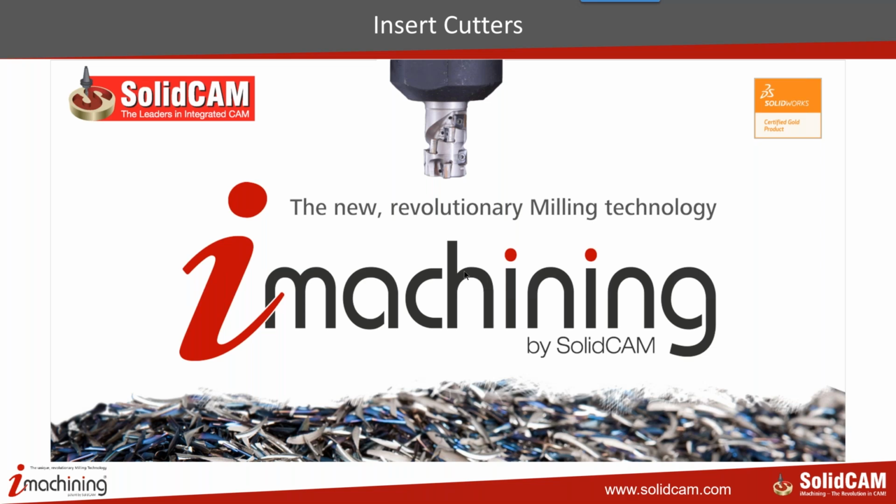However, since the variability of the geometric and mechanical properties of porcupine indexable insert cutters and their inserts is much higher than that of solid carbide end mills, and since metals react differently to being cut by such porcupine cutters compared to being cut by solid end mills, those algorithms had to be modified to take into consideration all those new properties and had to be recalibrated.